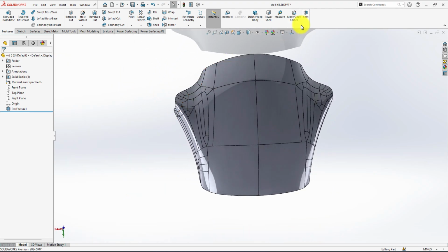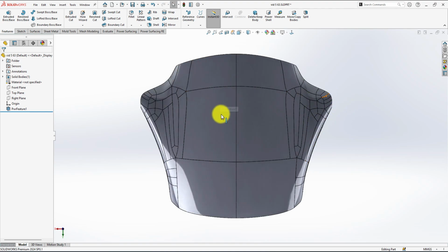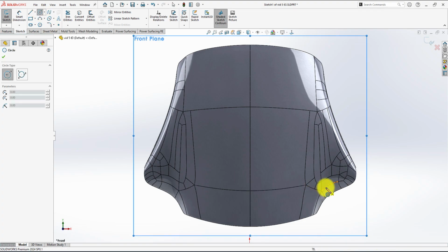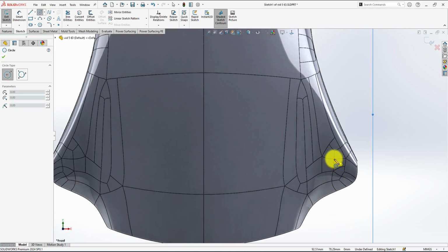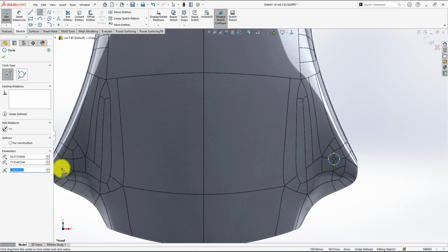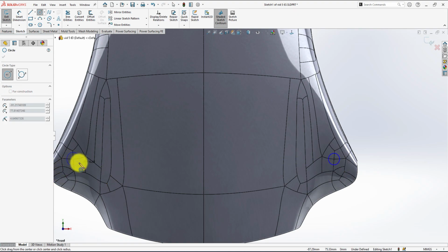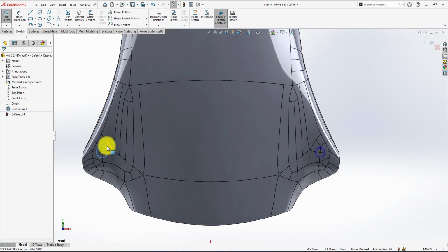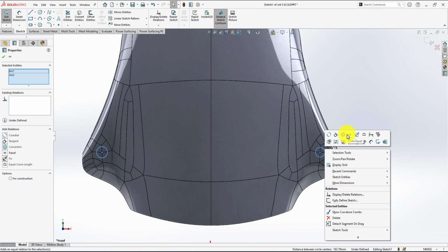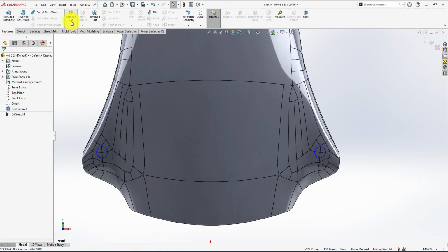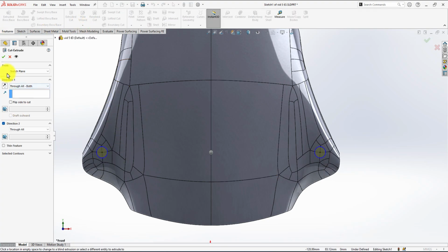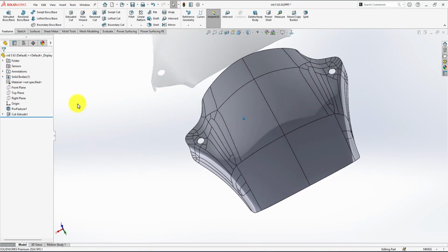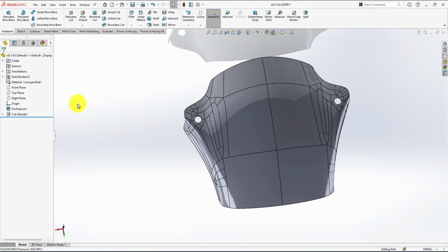Let me now go to the SolidWorks tools, go to front. I'm gonna sketch here, and I believe the circles were right in there, and let's make them all equal. You choose extrude cut through all both. Now here is my part, everything looks great.